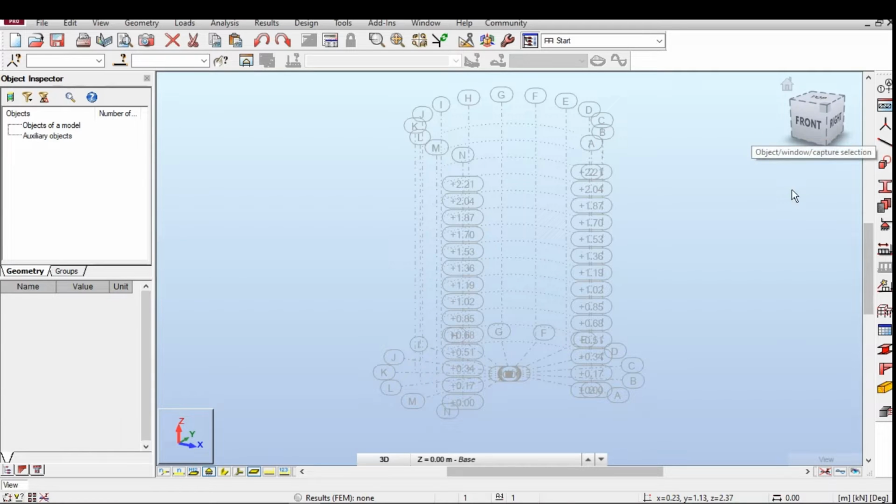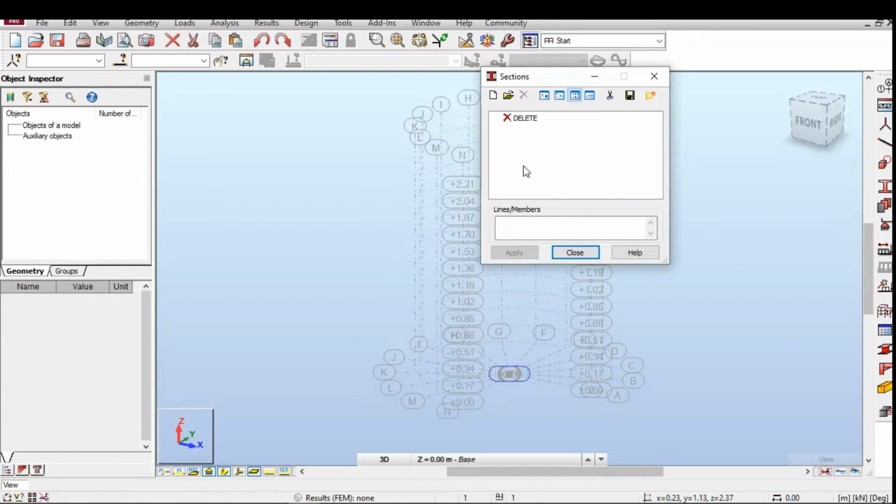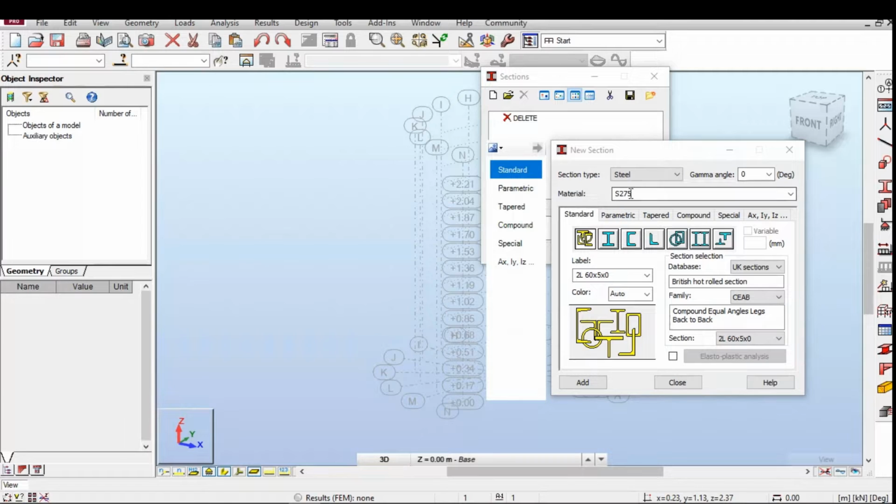Now I've defined our axis. The next thing to do is to define our member section. So find member section at the right of your screen. Now in this new box, click on that white icon. This will define a new section. Now there are a lot of things I can go through here, but for this project, let's work with Tube.